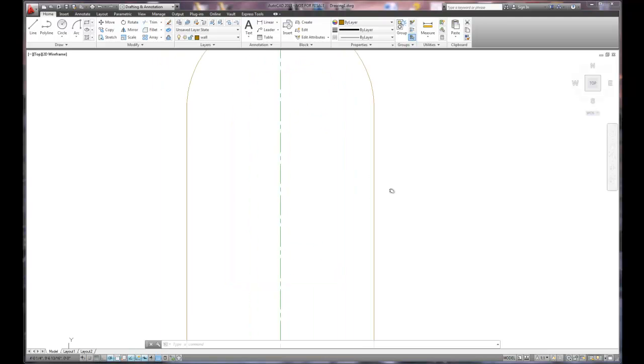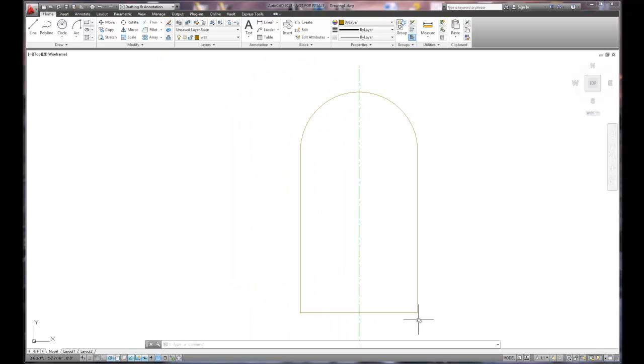So with the doghouse, I also need to offset the wall width. Well, the walls are going to be 3.5 inches thick. So I'm going to use the offset tool, which is a modify command. The first thing that it asks is what is the distance of offset. So it's going to be 3.50, and if I don't put anything, it knows it as inches. So 3.5 inches. I select an entity. I select a direction. If you do it wrong, you could offset it to the outside. We want to keep the outside dimension stable.